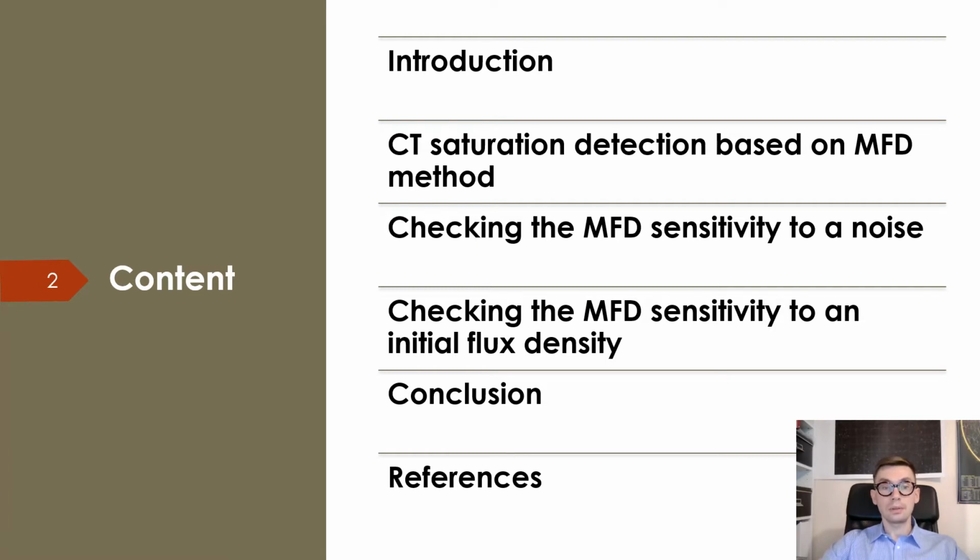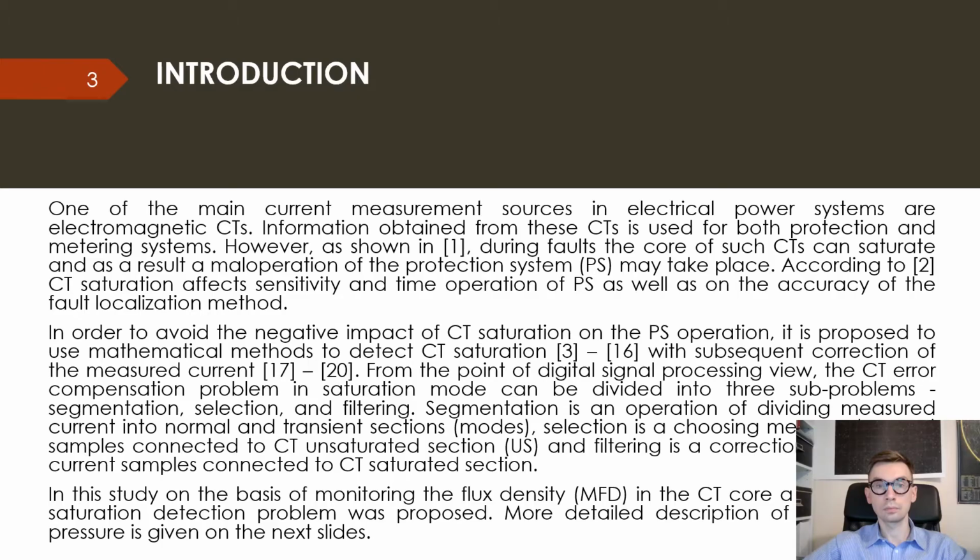It's possible to fix it using the possibilities provided by digital substation, based on the computational method of magnetic flux density estimation. The purpose of this research is to provide a method that can detect the saturation of the current transformer core with high reliability.